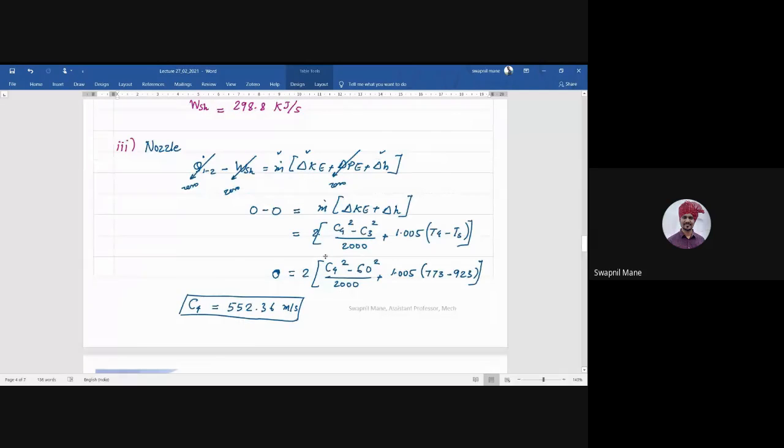Okay. Velocity in meter per second, potential energy in kilojoule per kg. So it is mgh. Okay. So m is coming outside, so it will be g by g into z. Z is the reference datum, z2 minus z1. So potential energy, for what component will it come? For pumps.